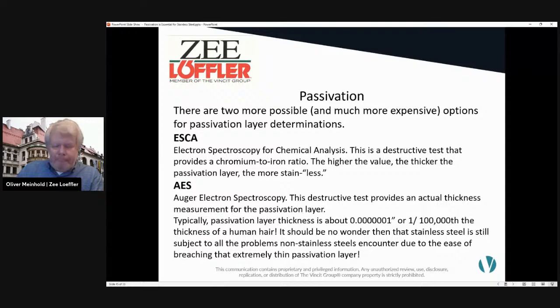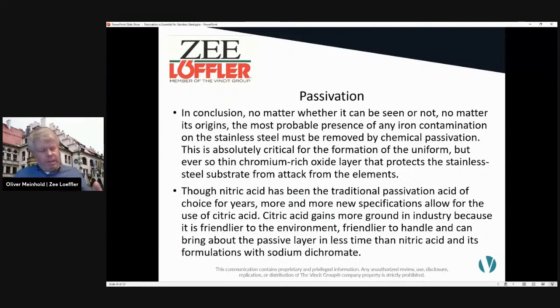What you can do is use other tests. They basically tell you if there are any impurities. It's only spot tests, so you don't get the whole picture of the tank, but they use little coloring agents that react with a different color if they touch an iron molecule, which is immobilized inside of the passive layer. But this is a tool just to get an idea how well you did the pre-cleaning, and it's only a few spots. From a statistical standpoint, it's not very informative, because you don't want to do hundreds of these tests to check a big tank.